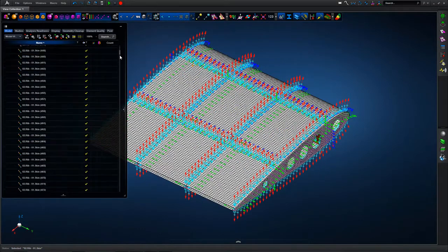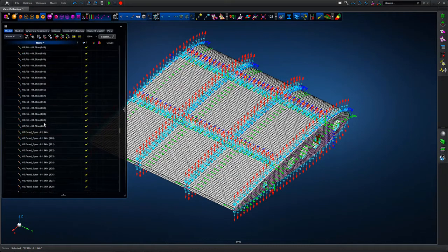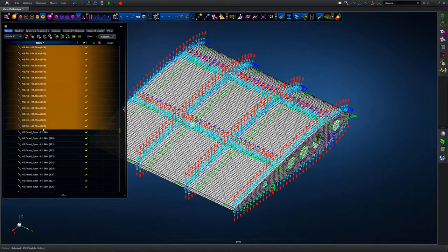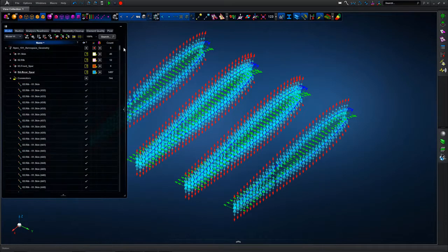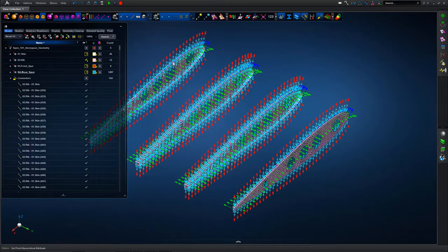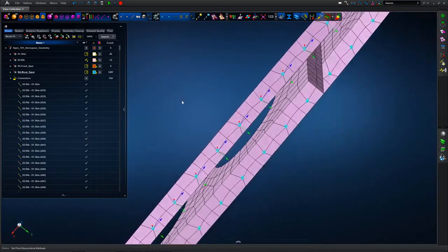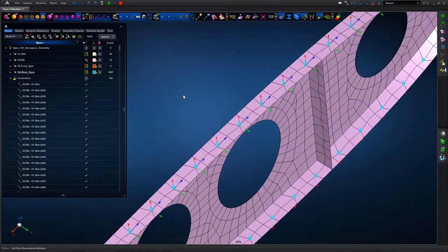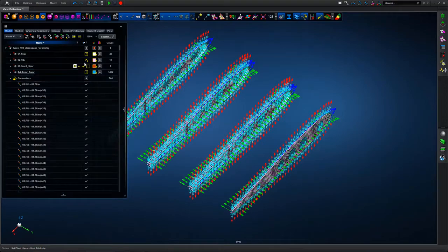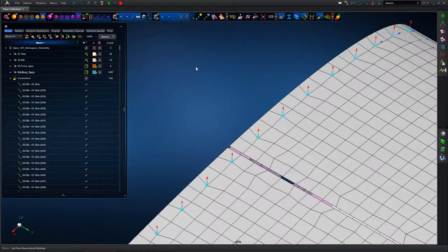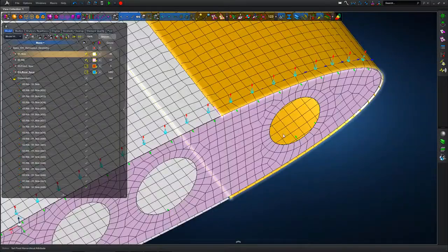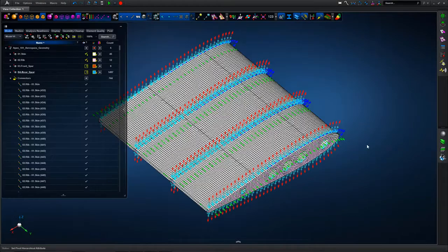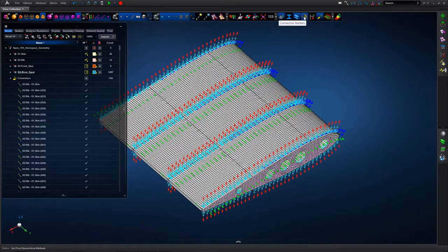And then going to the connector form, and again we've got the pairs used in the joint definition to name the fastener. So just showing the rib to skin fasteners again, putting the ribs into view. See the resultant topology. So the defeaturing exercise as part of the macro has given us a much more regular mesh definition for a far smaller model in terms of the node count and degrees of freedom. So this model would run much quicker than the original model with the fine mesh definition around the fastener holes.